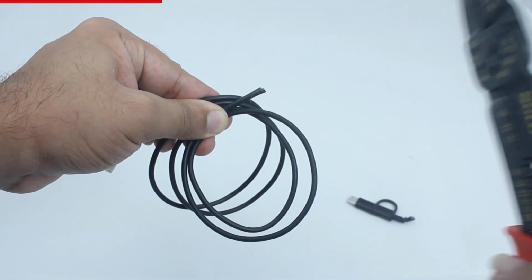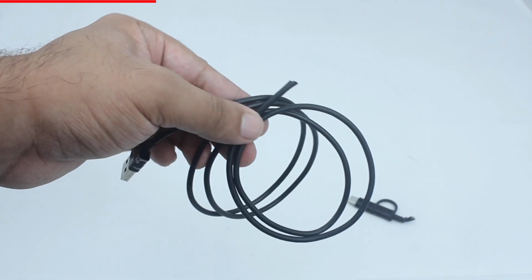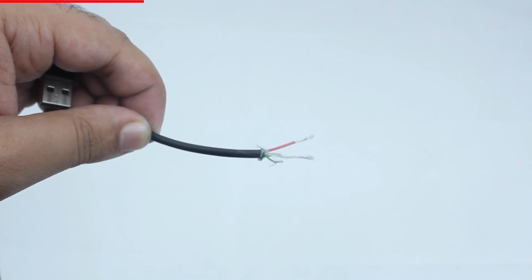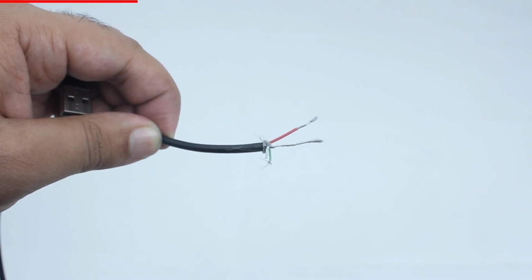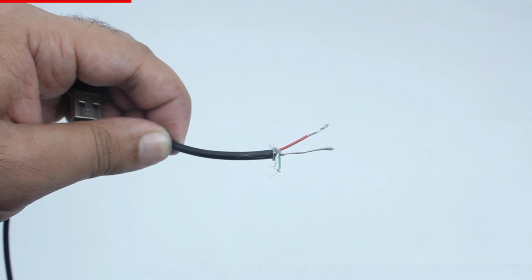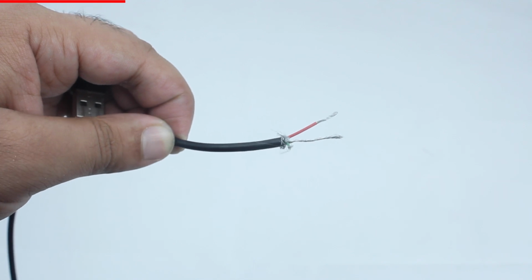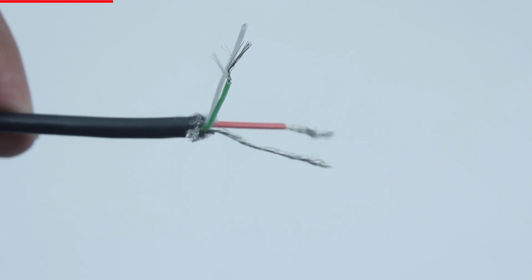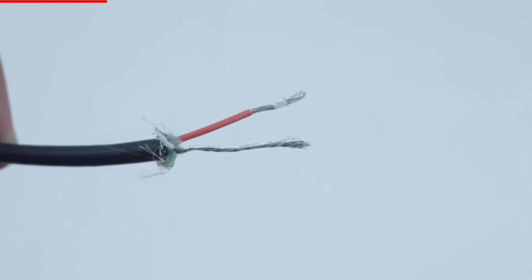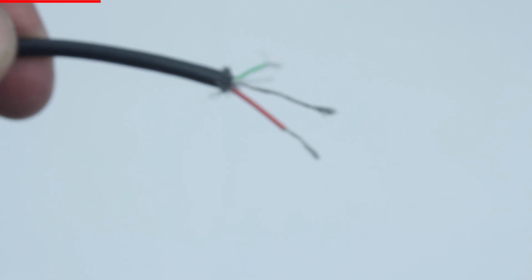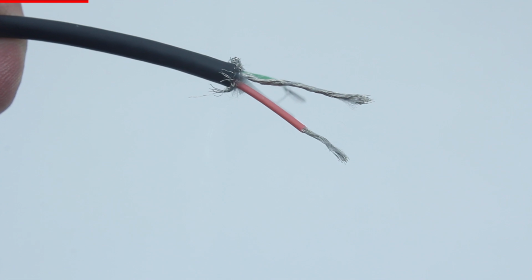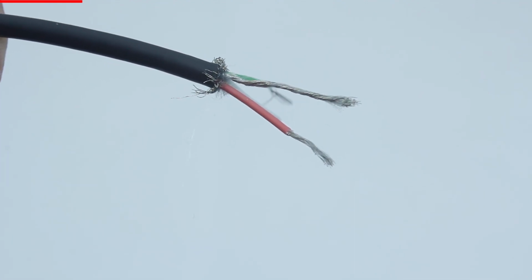Now for the USB cable, you snip away this thingamajig at the output end and then strip the insulation from the cable. You might find some metallic shielding on the wire, strip that away too until you're left with a group of 4 or 5 wires that look something like this. The red wire would always be carrying plus 5 volts and the ground would be a black one most of the times. But in this particular case, it turned out to be this uninsulated silver colored group of wires. That surprised me a bit too. But anyway, it's always a good idea to test the voltages using a multimeter as well.